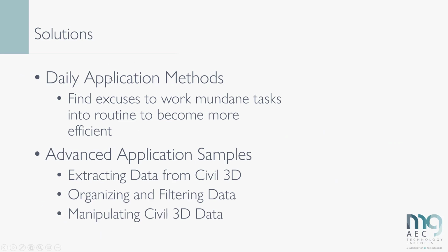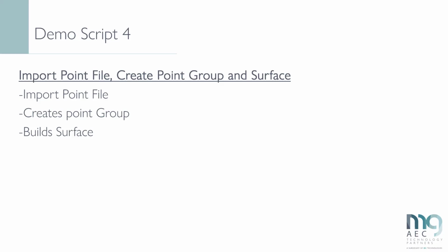So some of these other solutions, we can find these excuses to work mundane tasks into routine and have them become more efficient. So as we saw with that previous one, a common thing we're doing, creating stakeout points for our surveyors, we can automate that, tweak that script, and do any kind of export we want of that data. So we can extract data from Civil 3D, we can organize and filter data, or we can be manipulating that Civil 3D data. So we can really do a lot of these things here.